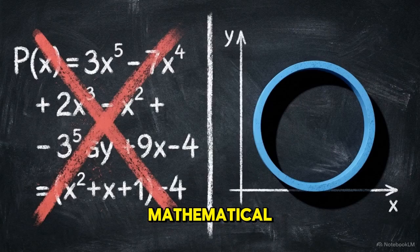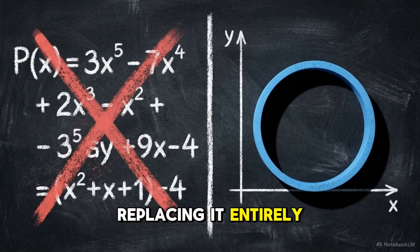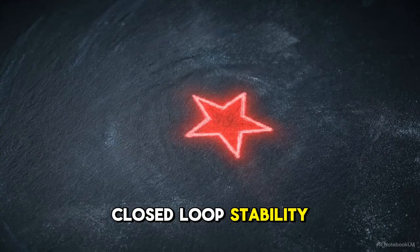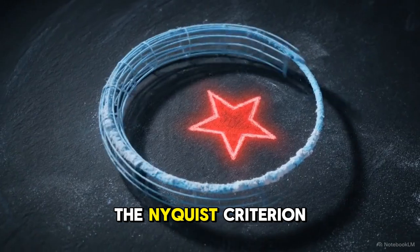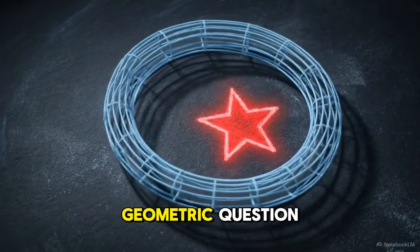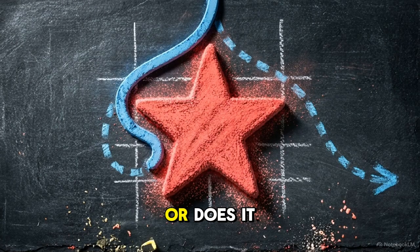We bypassed the mathematical nightmare of solving high-order polynomials, replacing it entirely with intuitive two-dimensional geometry. Closed-loop stability can be perfectly decoded using only open-loop data. The Nyquist criterion transforms a complex algebraic war into a clear geometric question. Does your open-loop curve trap the critical coordinate, or does it let it go?